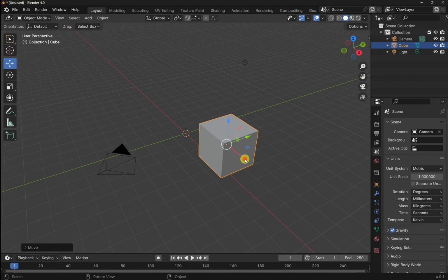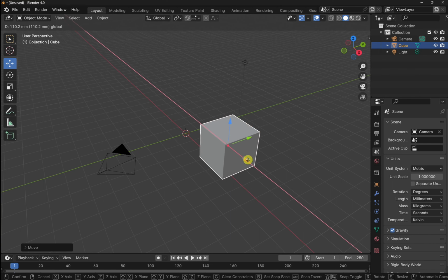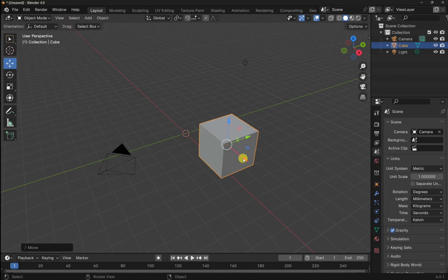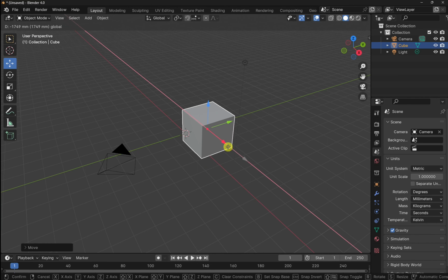And if I start to move this, if you look to the top left, we're now moving this in millimeter increments. So I'm holding down with the mouse. If I drag this over and then type on my keyboard 10, you can see that we've moved 10 millimeters. And by the side of it, you've got 10 equals 1 centimeter. So that's moved that 1 centimeter, or 10 millimeters, along the X.